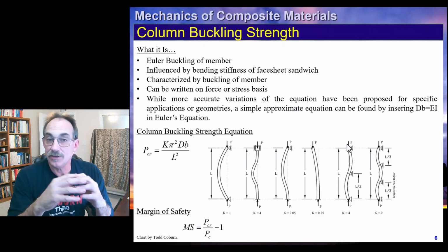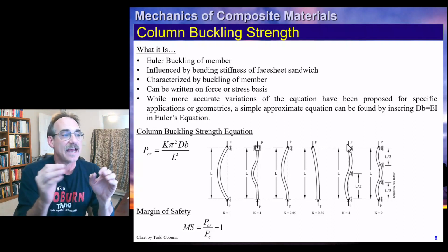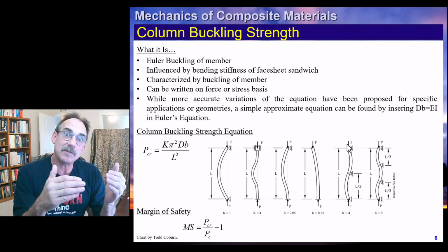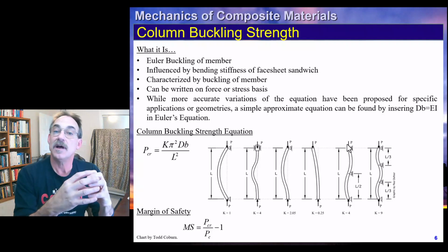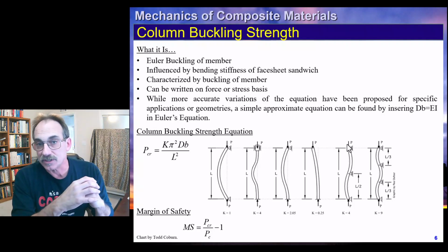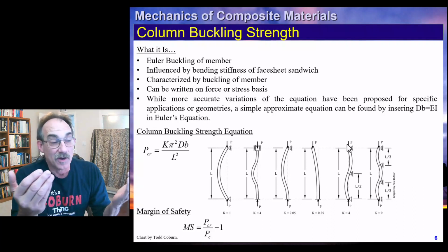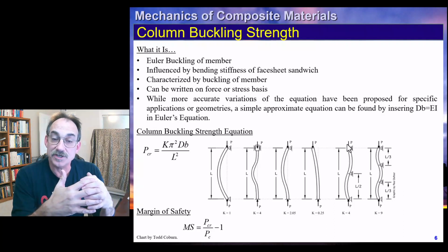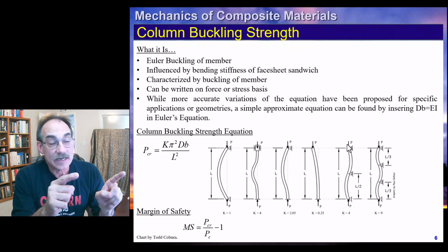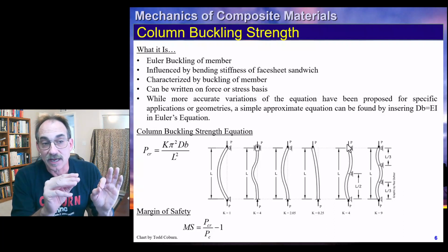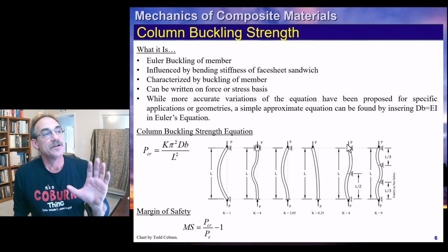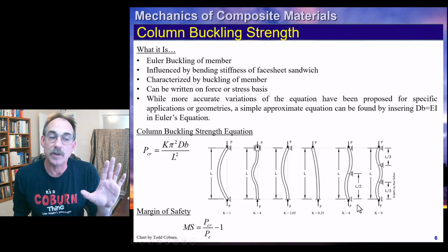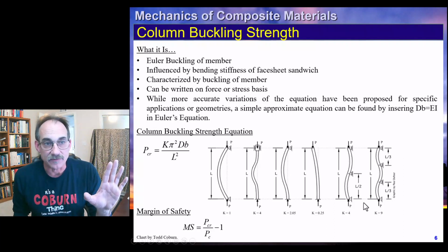And then if we go and try to use a more precise method, we can say, oh yeah, it's kind of in family. It's a little different than I thought, but it makes sense because I didn't account for this with the approximation, and this is why this looks like a valid, better answer. Or if we can't seem to get that other equation to work in a way that makes any sense, I recommend sticking with this as a likely more accurate method, unless we have vetted that other equation and the implementation of it. So this is a great practical way that we can evaluate the buckling of sandwich structures.